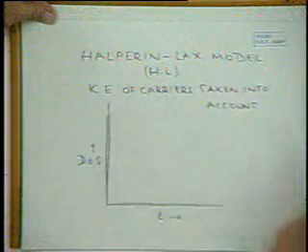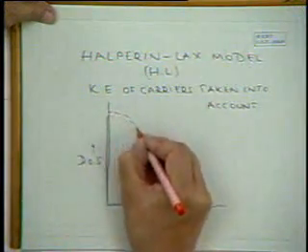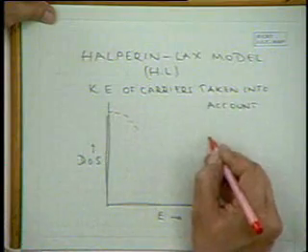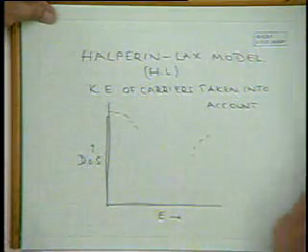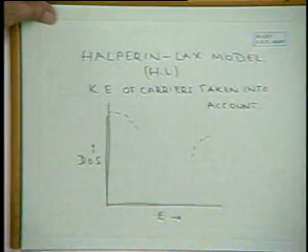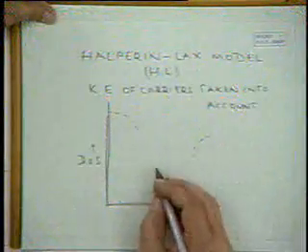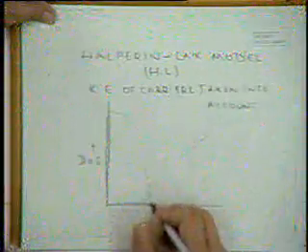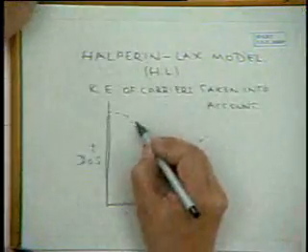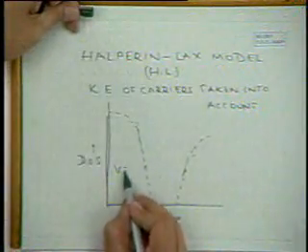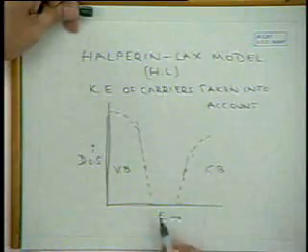What is done is it is a parabolic band at high energies, parabolic band here at high energies, and it is the Halperin-Lax band tailing here, okay, and there is interpolation to match. So this is the valence band and this is the conduction band, okay, and obviously these are the band gaps. So this is the Halperin-Lax band tail model,